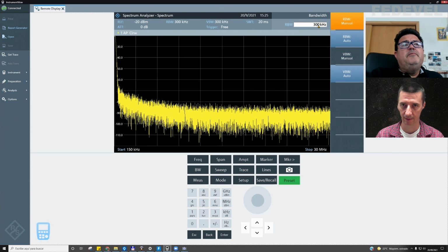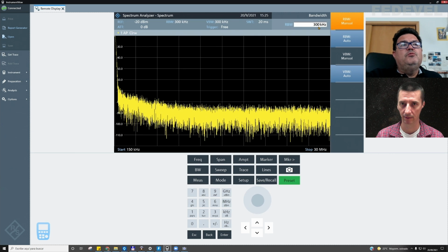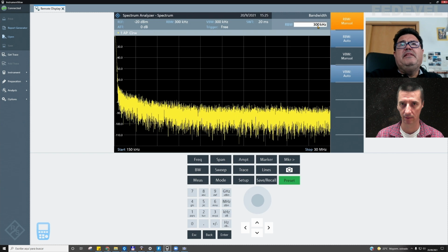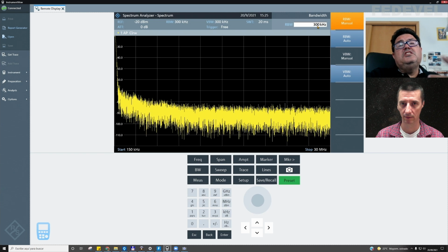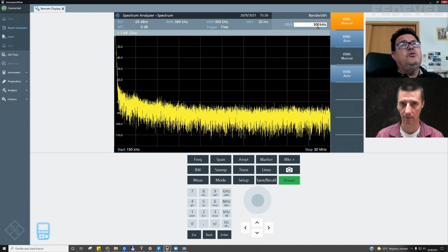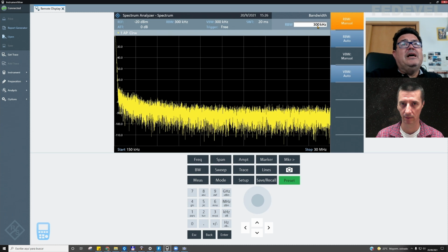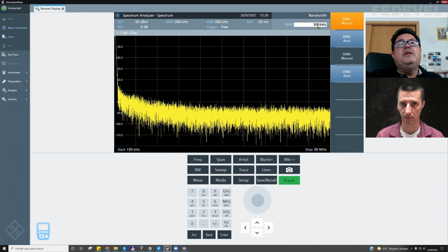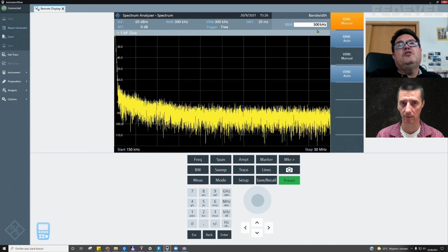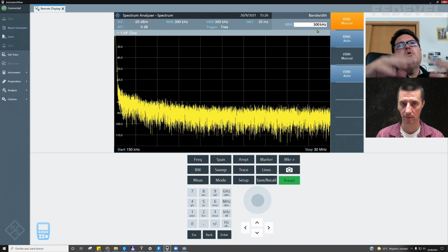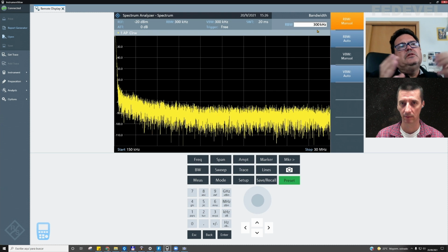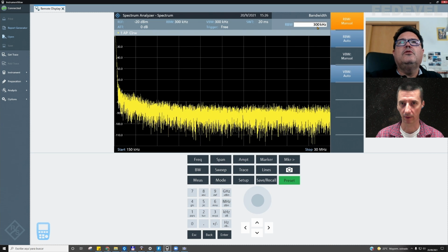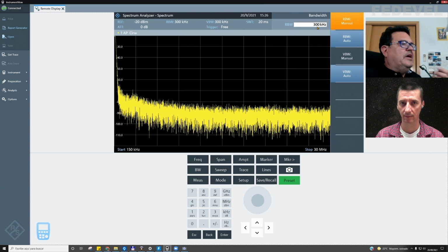Okay. So typical values, for example, for the resolution bandwidth are 200 hertz, 9 kilohertz, and things like that. But this is important for going to a laboratory or doing a formal certification. When you are doing debugging, you can use similar values, not exactly the same, because you will see the noise and you will be able to work to reduce the level. So now I will be using 300 kilohertz. Now I switch on my device.